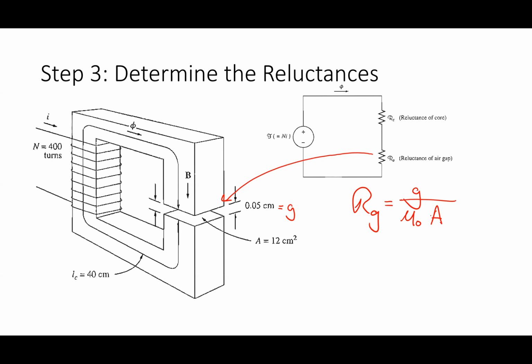So the reluctance of the gap is going to be much greater than the core. Because mu naught is smaller, RG is going to be much bigger. Think about it in an ideal world, and this is what I wanted to show too: the core is just like a wire. The wire you ignore, you don't think of the resistance of a wire, just like you don't think of the reluctance of a core. The job of the core usually is just to direct the flux to where it's useful, like in the gap. Same thing in that Tesla motor. The iron just directs the flux into that gap where it's useful.